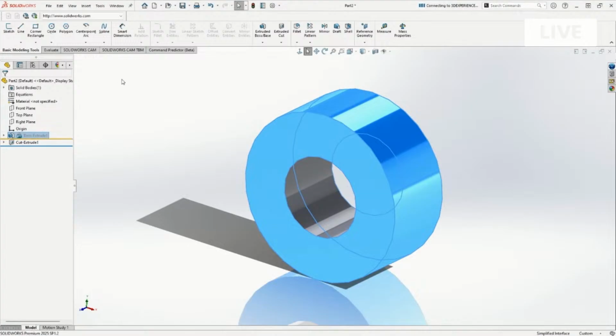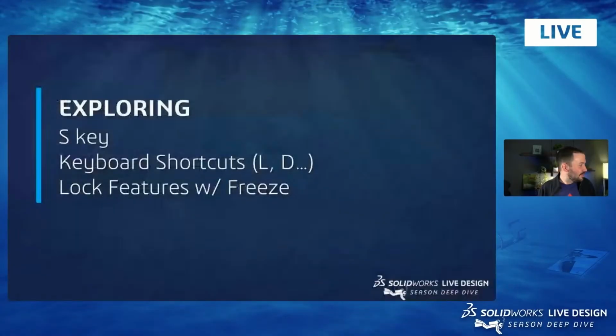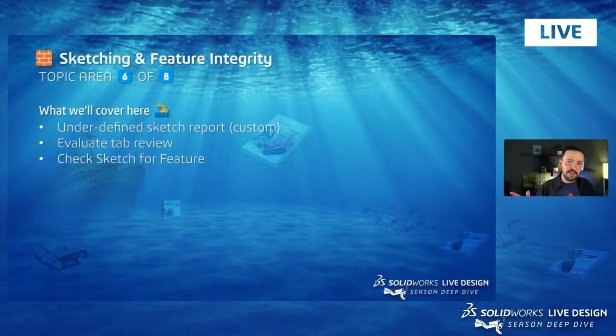Now, the usefulness of this is, for example, let's say you have a very hack and slash sort of surface model part where it was surface extrude and it was surface cut, and you know the deal. You just keep basically hack and slash surface modeling. This is a potential usage for the freeze toolbar, because if you don't really care and it's not rebuilding the feature tree every single time, it can make it a little bit easier for the model to regenerate and thereby be accessible to you for further options. So I definitely recommend looking into the freeze bar. It's under the general tab in options, or once again, as you saw I did there, just search the options for freeze. And we don't have a lot of options with freeze in the name, so you'll find it.